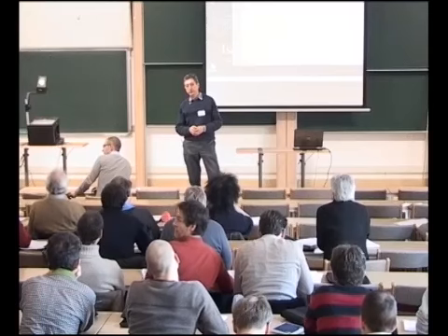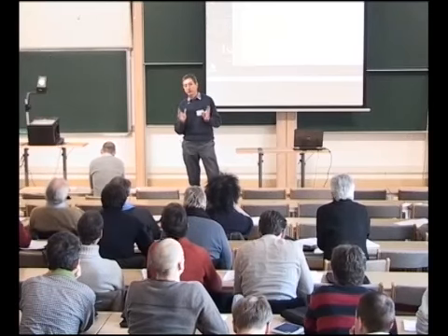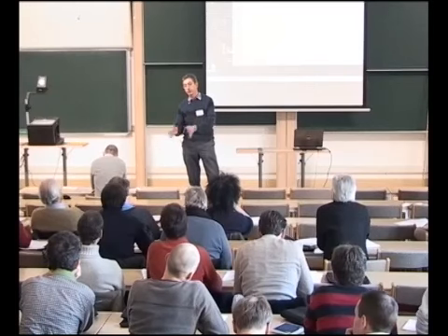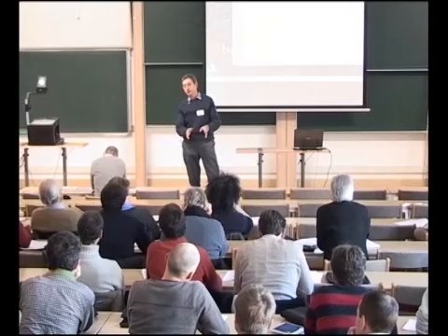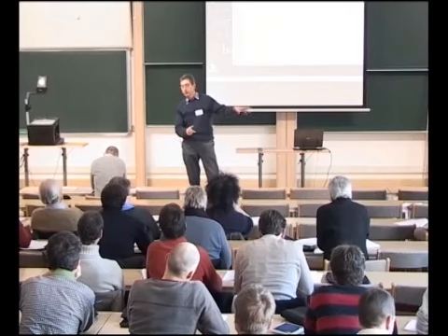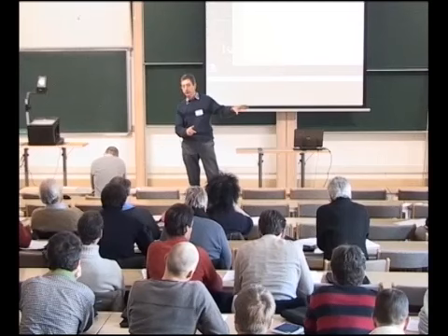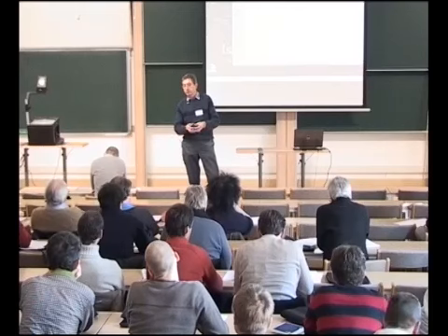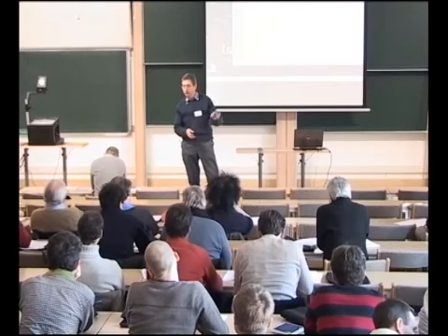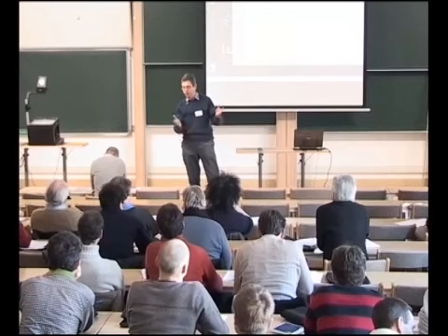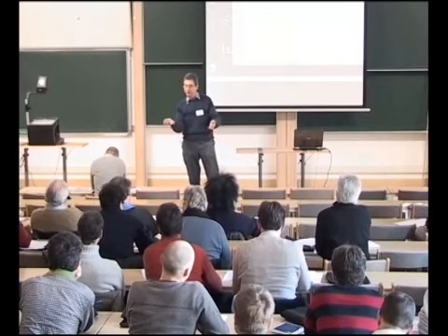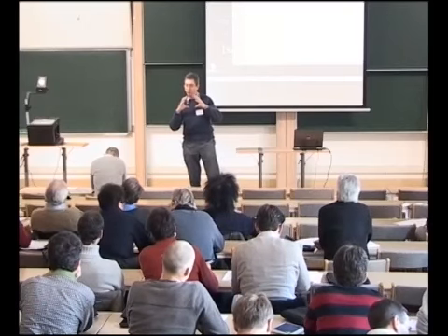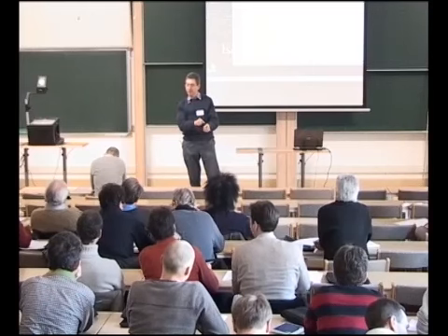Well, can you tell me why you believe it to be inconsistent? Because wherever I saw asymmetric stress tensors, I saw couple stress. Oh, yes, okay. This is true. The standard thing is to have what I call a full Cosserat model, where you have the couple stress, a non-symmetric stress tensor, and possibly the rotational inertia, though often they get rid of the rotational inertia. Now, I happen to believe, it's my opinion, that the opposite is true. I can see rotation.